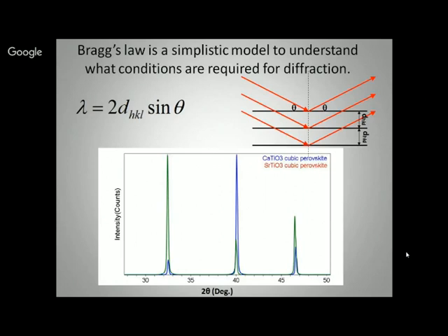If your crystal obeys this Bragg's law, then you will have some X-ray diffraction pattern. But if it is not obeying this law, it means your material is amorphous in nature. I think you can see a plot below it. Along the y-axis you have the intensity of the X-rays which get diffracted from the material, and along the x-axis you have the theta value.